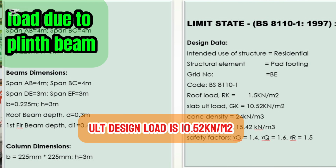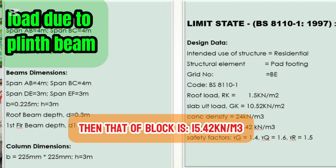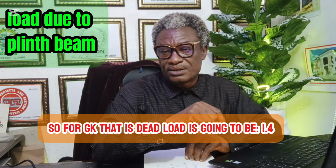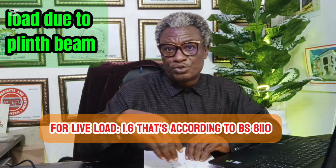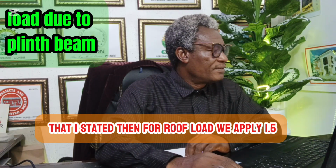Then the roof load is 1.5 kilonewton per meter squared. Then the slab ultimate load is 10.52 kilonewton per meter squared, whereas the specific weight of concrete is 24 kilonewton per meter cube. Then that of block is 15.42 kilonewton per meter cube. Then we will apply the basic factors of safety. So for GK, that is dead load, it is going to be 1.4. For live load it is 1.6. That's according to BS 8110 that I stated. Then for roof load, we apply 1.5.